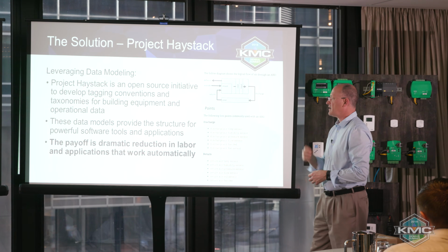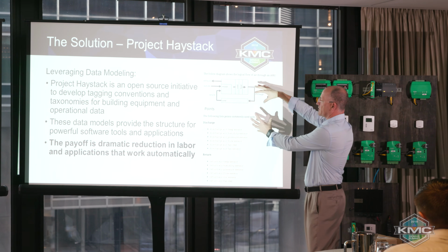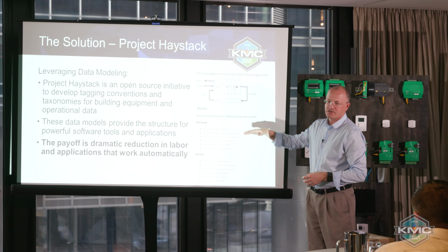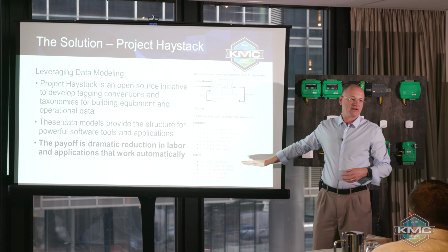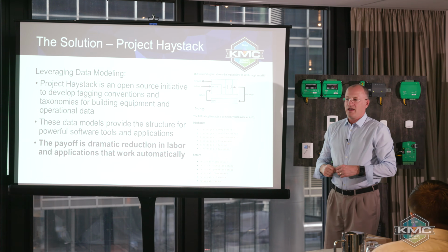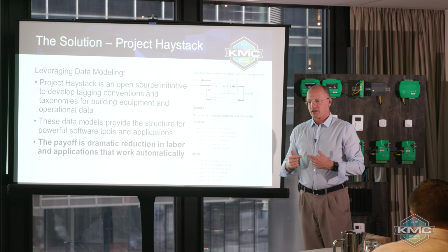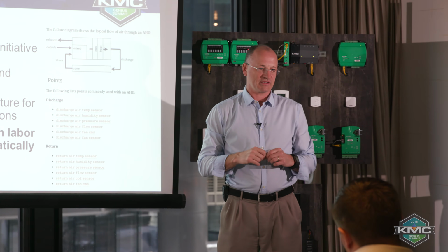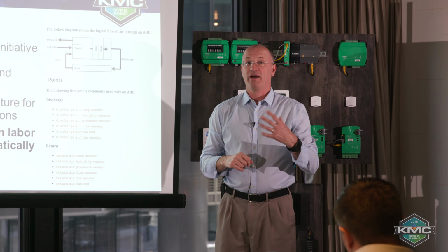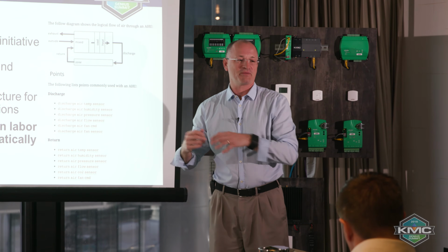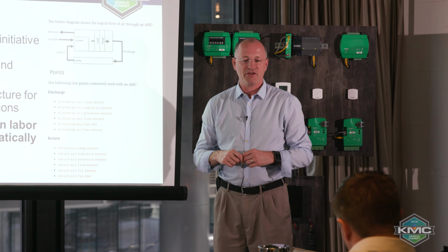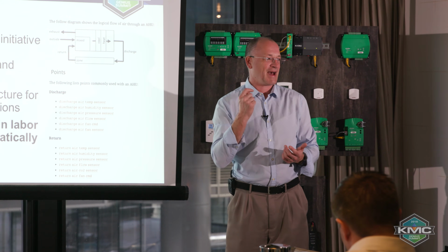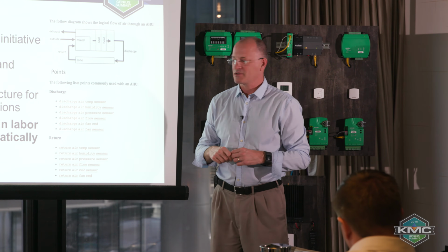It's the idea that on a bigger view of things, I'm dealing with, let's say, an air handler or a chiller, and it's made up of a discharge air sensor, a mixed air sensor, a fan command, and a hot water valve command. And when you start getting into the practical application, you'll see that this data modeling really pays off from an engineering best practices standpoint, or better said, if you have engineering best practices, the payoff will be that much better. Because now you can teach an application to do the same thing over and over again if there's any typicalness, and it happens in an instant. And I'll give some examples of that.